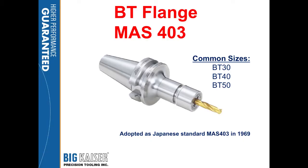The BT flange is common to Asia. We jokingly refer to it because I can't find a better name for BT than bonsai taper. Don't know what it really means, but that's really what it is for BT. And it's identical to the CAT. The same diameter, same rate of taper, it's all the same. The only difference is the automatic tool change.